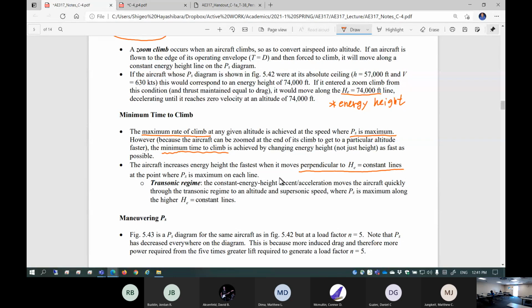If you are designing a supersonic capable airplane, climbing with maximum rate of climb does not necessarily mean the same as minimum time to climb, because minimum time to climb requires you to go through the transonic region. First, you climb with maximum thrust going over the peak point of PS, but as the transition from transonic to supersonic comes in, you actually want to accelerate, not climb, then hit supersonic and begin climbing.